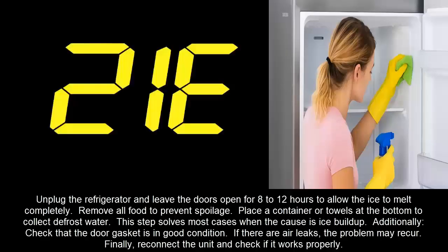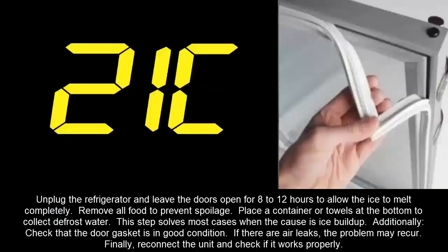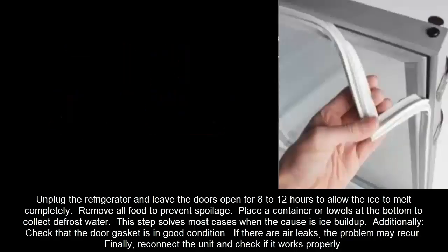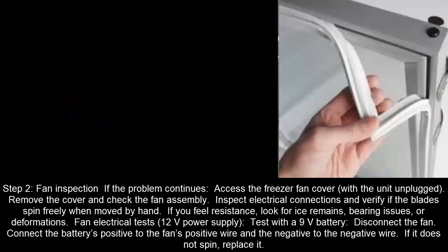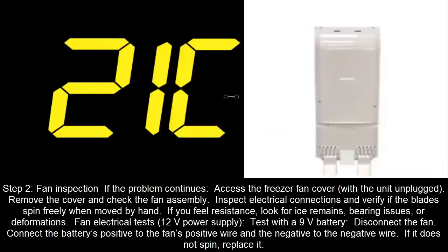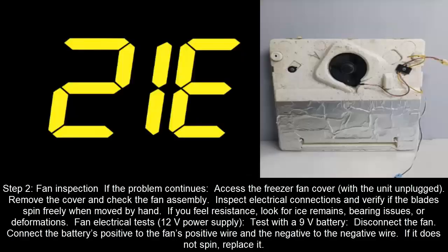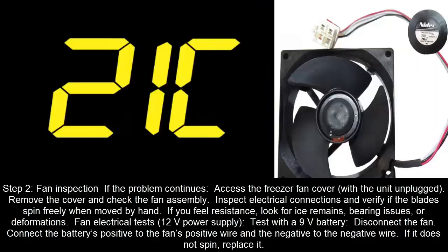Additionally, check that the door gasket is in good condition. If there are air leaks, the problem may recur. Finally, reconnect the unit and check if it works properly. Step 2. Fan inspection. If the problem continues, with the unit unplugged, access the freezer fan cover, remove the cover, and check the fan assembly. Inspect electrical connections and verify if the blades spin freely when moved by hand. If you feel resistance, look for ice remains, bearing issues, or deformations.